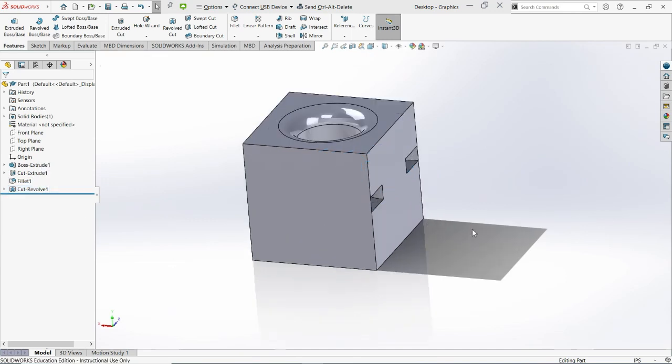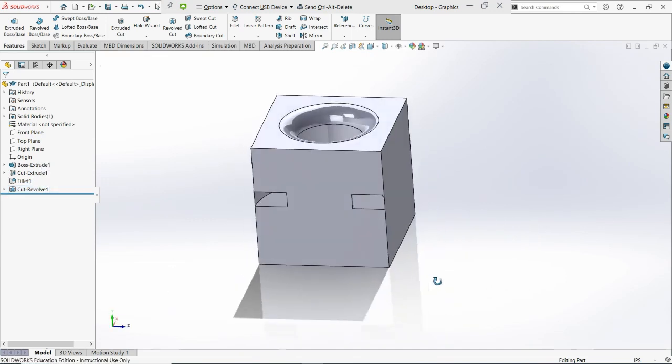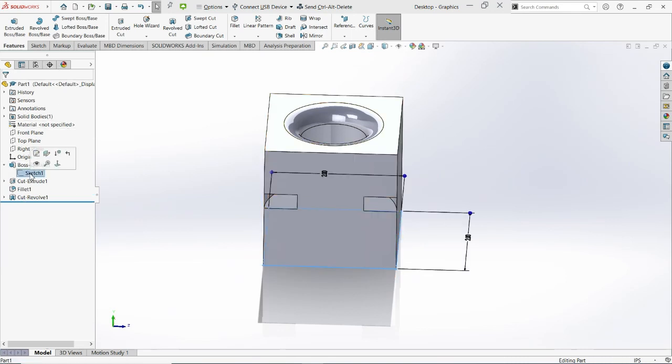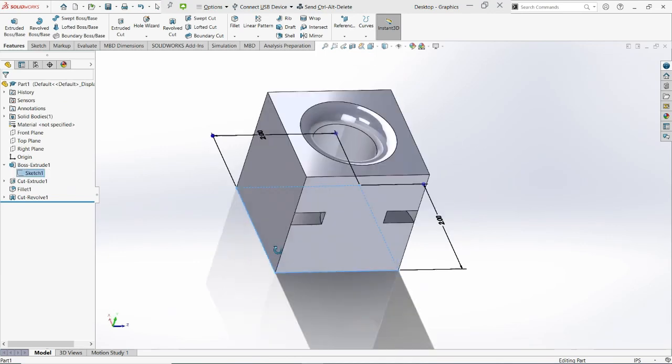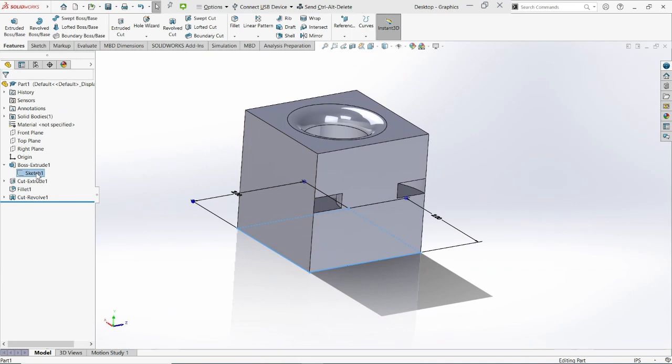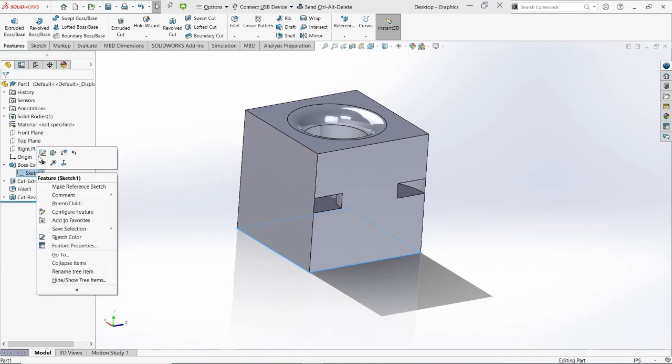One very nice thing about Solidworks is that you can change any part at any time or any feature. So if we go over into this left panel called our feature tree, we can go back to our original feature, which was our first extrusion. If we click the drop down, we see this first sketch. And if I click on that sketch, you can kind of see the outline of it, along with our 2 dimensions. And you right click on it and click the Edit Sketch button right here.